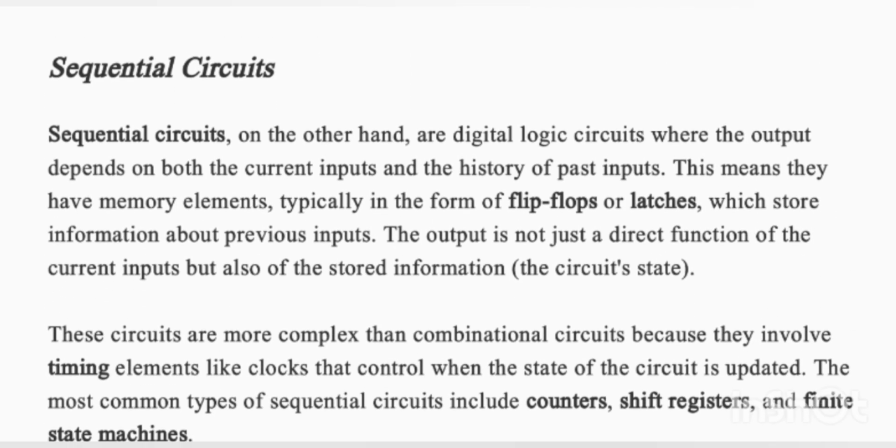Sequential circuits. Sequential circuits, on the other hand, are digital logic circuits where the output depends on both the current inputs and the history of past inputs. This means they have memory elements, typically in the form of flip-flops or latches, which store information about previous inputs. The output is not just a direct function of the current inputs, but also of the stored information, the circuit's